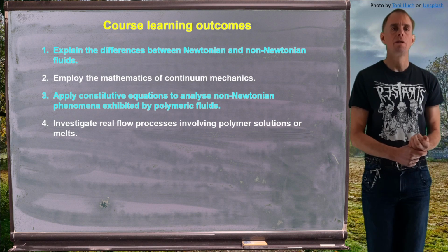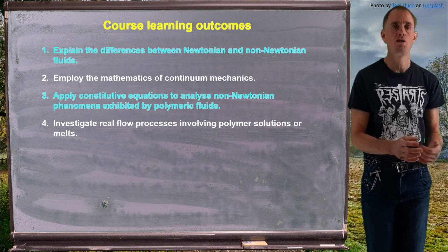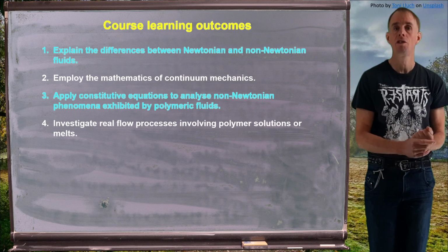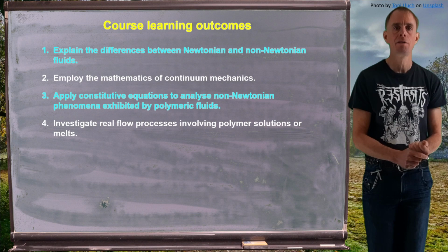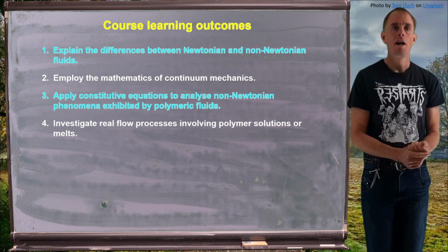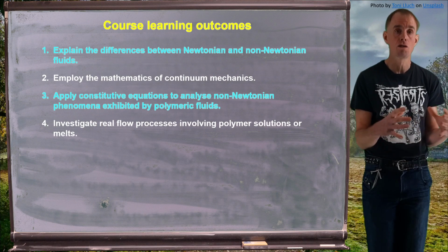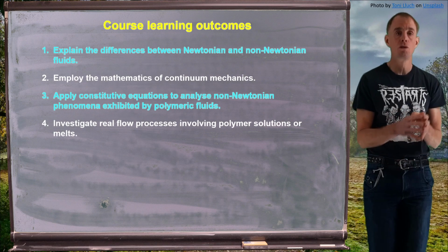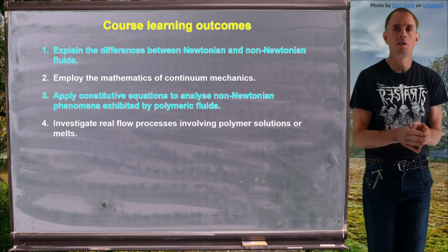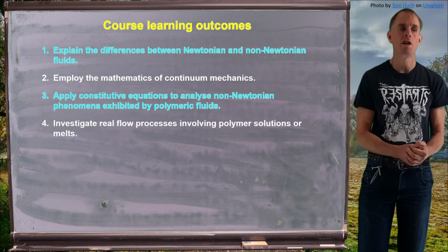What I'd also like as an outcome is for you to have a toolkit to investigate real flow processes that involve polymer solutions or polymer melts, be they shape-forming processes, be they understanding how pressure drops vary down a conveying line when you've got a shear thinning liquid, maybe understanding the flow patterns in a concentric annular blow moulding die, or something of that nature. And so you'll be able to put into practice some of the basics that you've learnt on this course to start to give insight into those engineering applications.